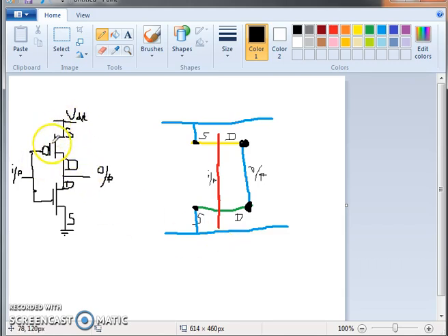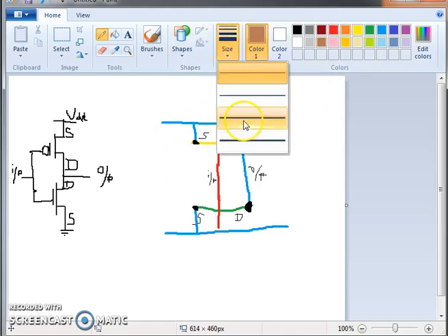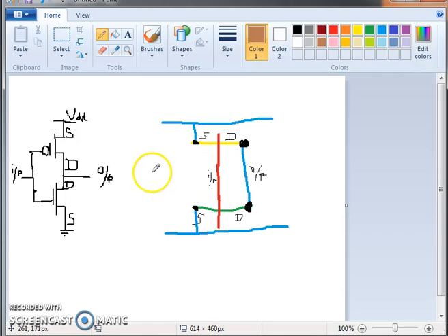Now, for the PMOS transistors, either you use P-well CMOS or you can use N-well CMOS. To show a well, you have a demarcation line, a brown color dotted line, which is also called a demarcation line, which indicates it's a well. It can be an N-well or it can be a P-well. So at the last, you show the well formation with a brown dotted line. Thank you.